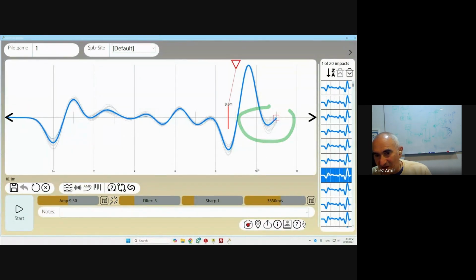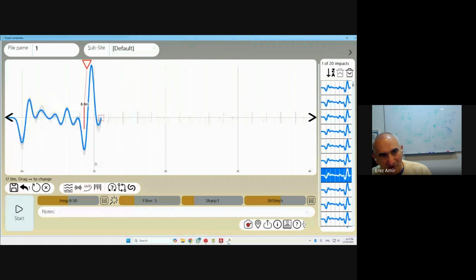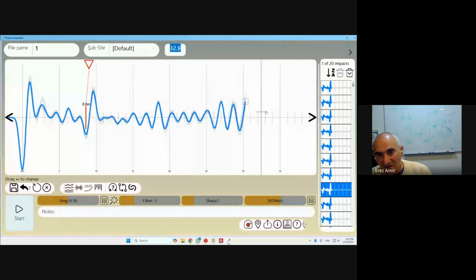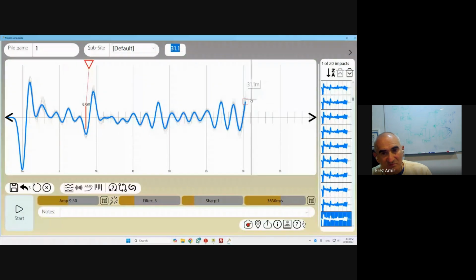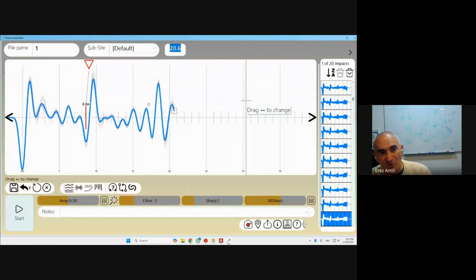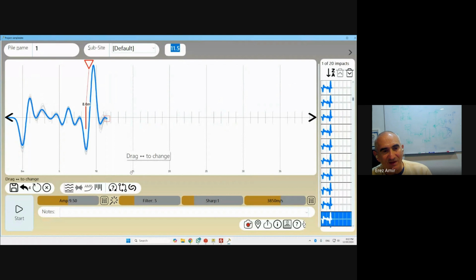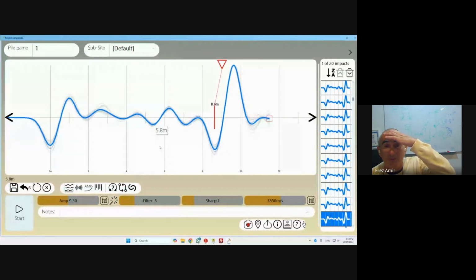We can only see that they are separating if we look farther up the pile, and even there, no, sorry, they're just one on top of the other. So in this case, we have a very consistent result. Because of that, we know that this is not random noise. This is data that we can trust. It's real data coming from the depths of the pile, and not some random noise that came from hitting the reinforcement bars or a broken piece of concrete.